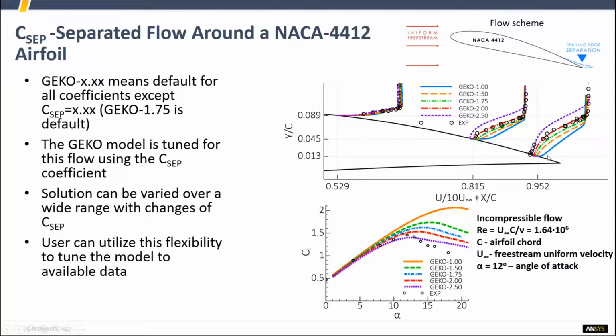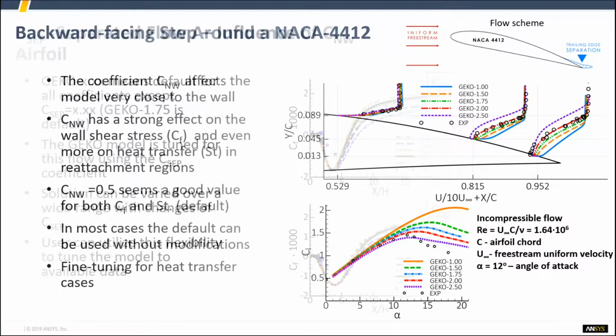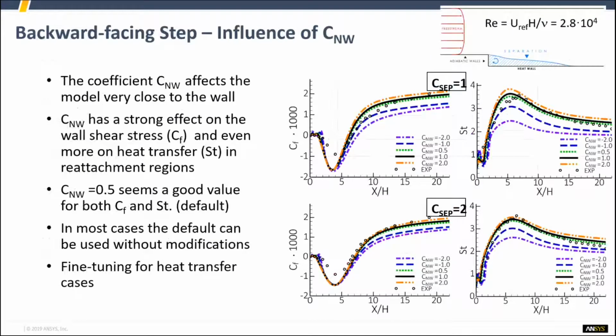Okay, so these are very subtle differences. And like I said before, when we play with the coefficients of a K omega model, we can destroy the model. When we play with the coefficients here, we can kind of change the separation behavior without affecting the other behavior too much. I don't know how they've done that. It's like magic, but this is a new model and something worth looking into if anybody's interested in CFD.